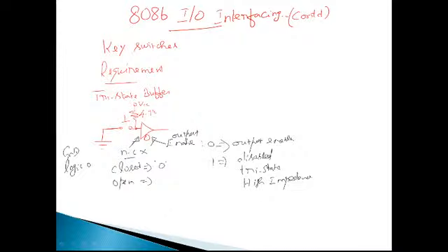Now hope you understand, when the switch is in the normal, not connected, open state, when the two terminals are not connected, naturally the 0 will not come. When the 0 is not coming, what would happen? The same potential, the VCC, will be appearing here. VCC is already equal to 5 volts. So almost the same 5 volts will be available here as an input, which indicates that it is logic 1. So when the switch is in open state, logic 1 will be connected to here.